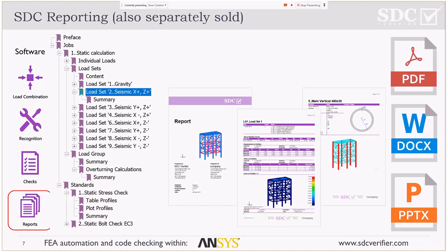And then for the calculation structure for every load set, you can set up in detail what views you want, what you want to select, what tables and table results you want, and copy that to all other load sets. So you set it up once. That maybe takes a bit more time. Let's say if you want to have a really nice report, you spend 10 minutes on one load set to show everything you would like to know.